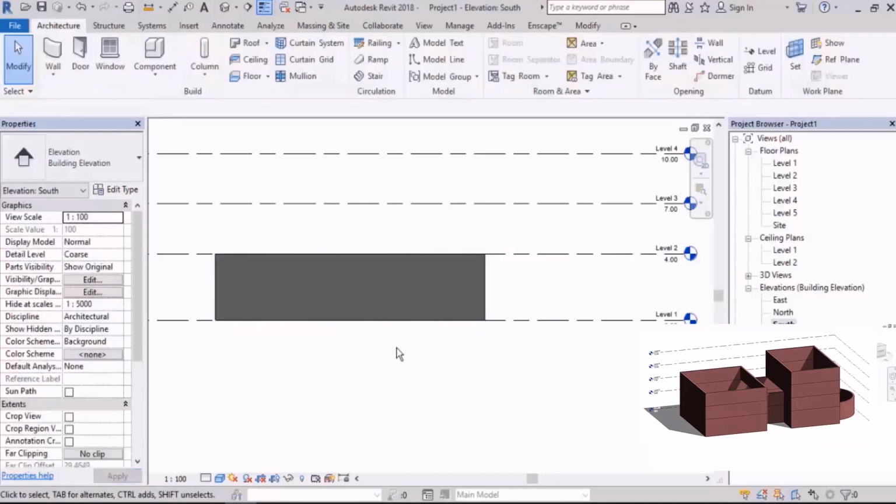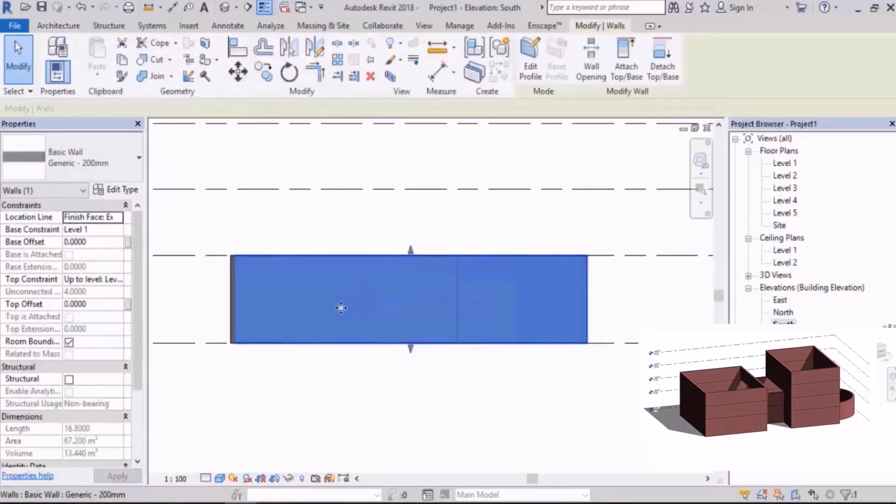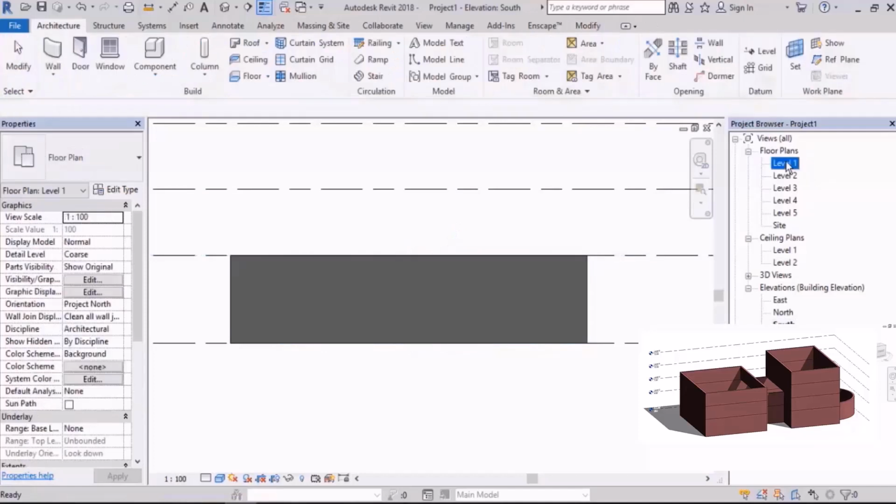And don't think that these numbers are just for nothing. Sometimes I've seen some people do something wrong. For example, they select the wall and drag this arrow to top, just like this. Well, it's wrong. It just has a top offset now. The level hasn't changed.